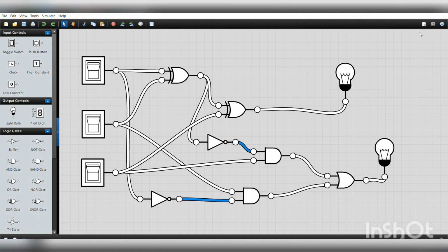We had earlier seen the design and implementation of a half subtractor, and now we are going to see the design and implementation of a full subtractor. A full subtractor generally consists of an XOR gate, NOT gate, AND gate and an OR gate. So the outputs are the difference and the borrow, where the difference equation is A exclusive-OR B exclusive-OR C and your borrow equation is C into (A exclusive-OR B) the whole dash plus A dash B.